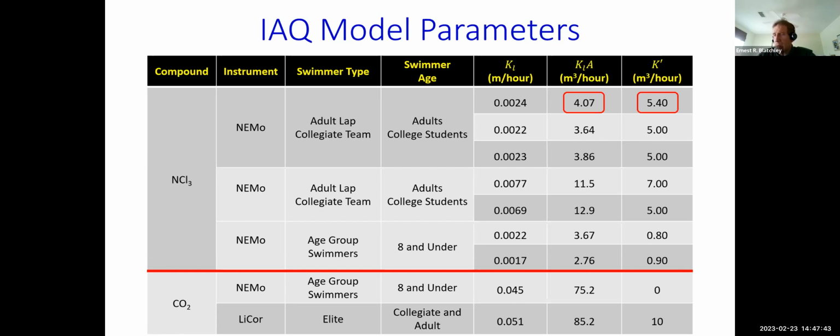So this describes the rate of transfer that's attributable to just circulation of water through the treatment system. This corresponding value is the mass transfer coefficient that describes the transfer of a volatile chemical that's attributable to one swimmer. So what we learn from this and from the other experiments is that it doesn't take very many swimmers to overwhelm the mass transfer that would be observed just in the baseline case.